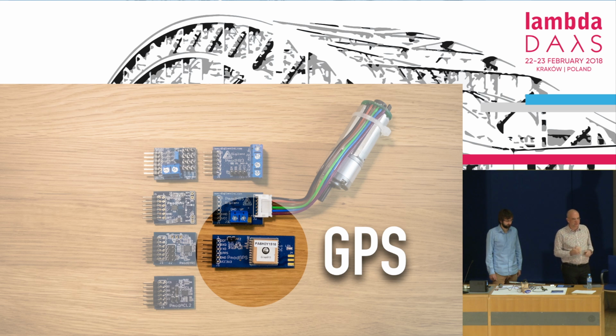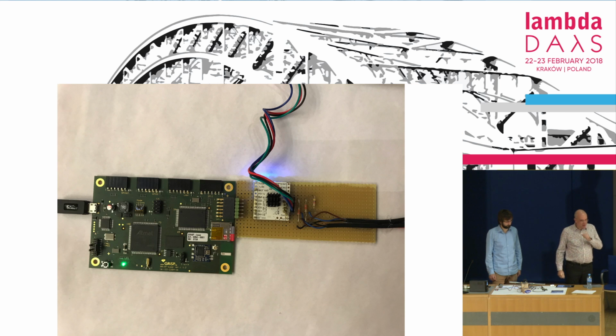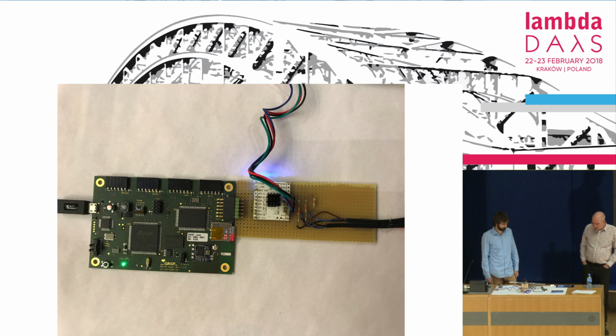And there's also a Pmod for GPS. So for example, if you're outdoors with a drone, all you need is the Pmod NAV and the GPS Pmod, and you always know where you are very precisely. You just need to do a little bit of filtering and nifty processing. The interfaces to the Pmods are pretty simple, and it's an ideal first way to do your first own hardware thing.